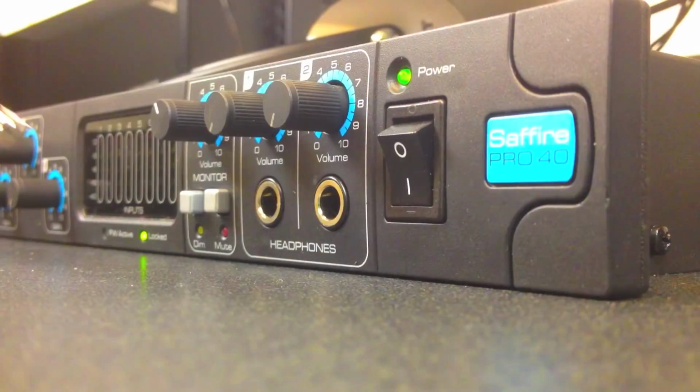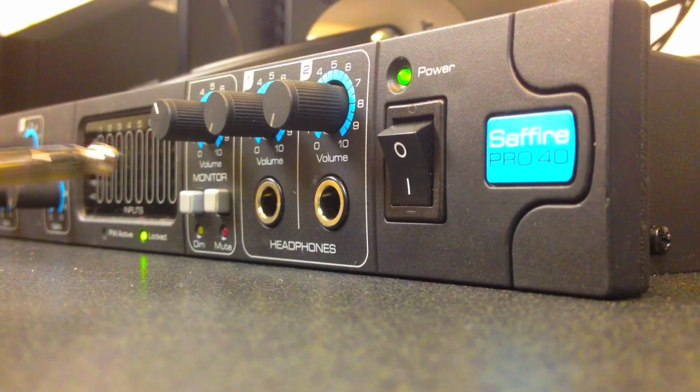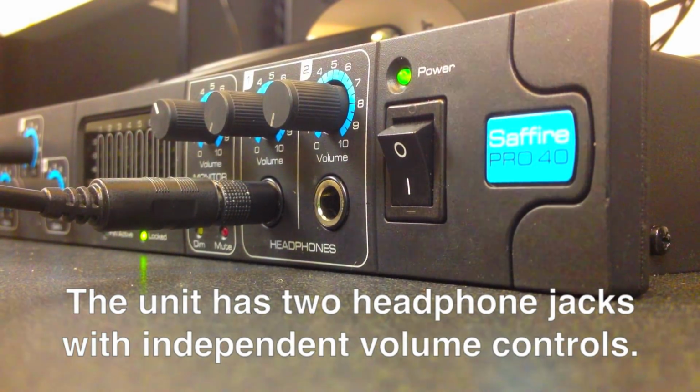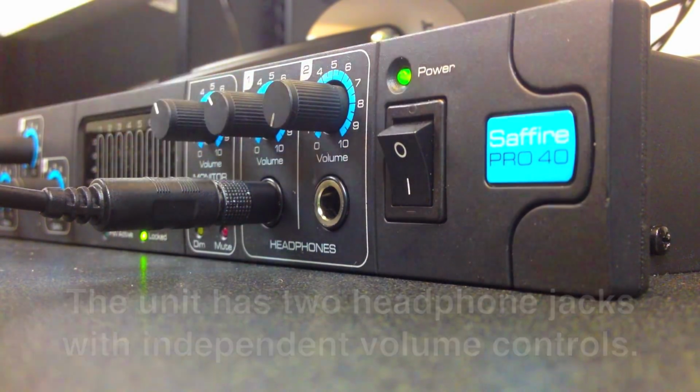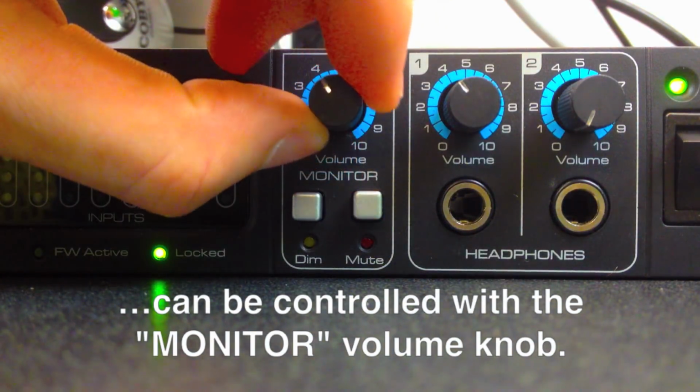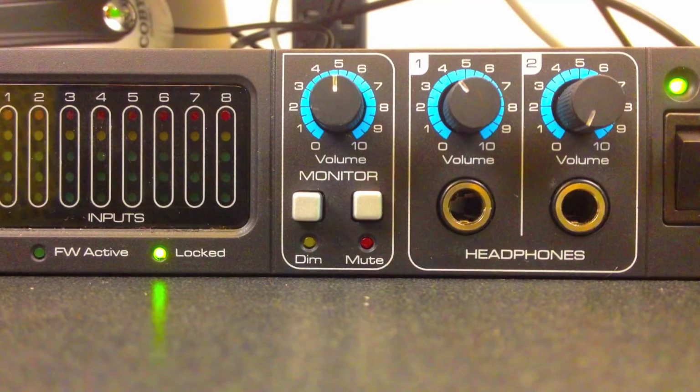If you're using the Focusrite as an output, you have a few options. On the front, there are 2 headphone jacks with independent volume controls. On the back, there are monitor outputs. These connect to the KRK speakers and should remain plugged in. You can control the volume with the monitor volume knob. If you aren't getting any sound out of one or both of the KRK speakers, check the connections and power switch on the back of the speakers.